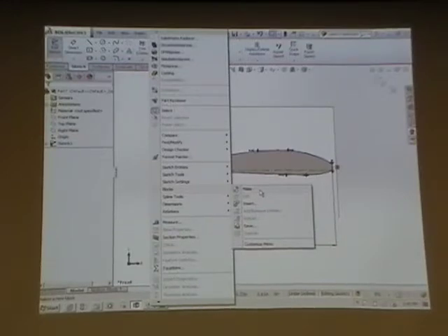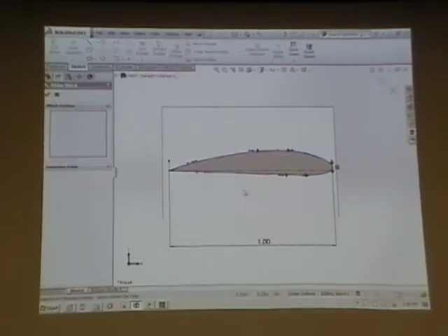Tools, Blocks, Make will bring up this selection box where you choose what you want to put into the sketch block. So I'm just going to click the 2 splines. And you have the option of choosing an insertion point down here. The insertion point is optional, but it's a good idea.